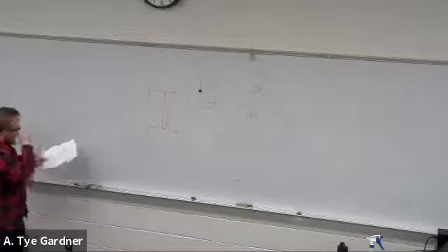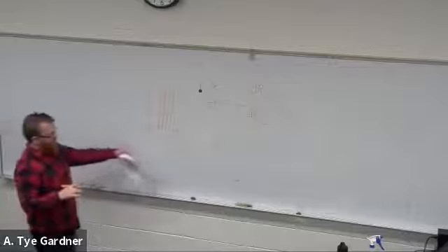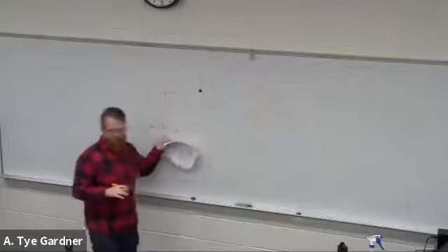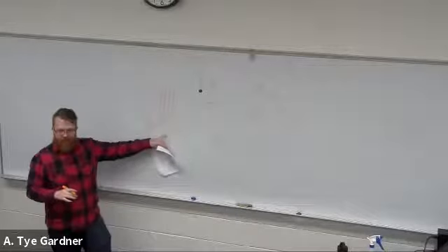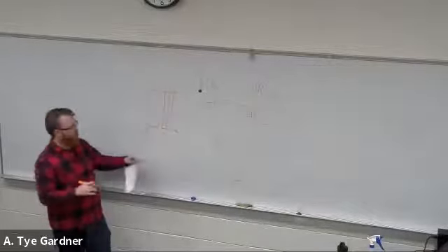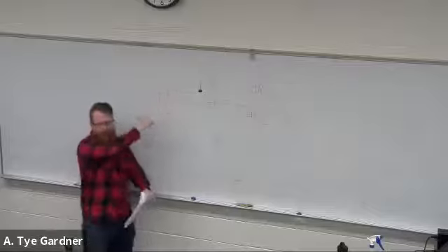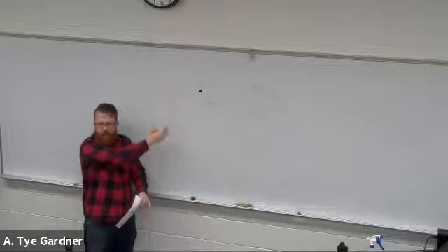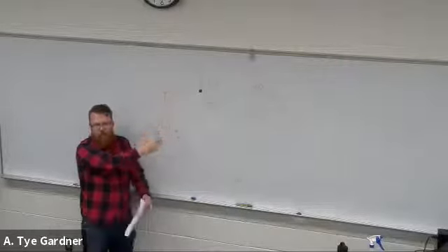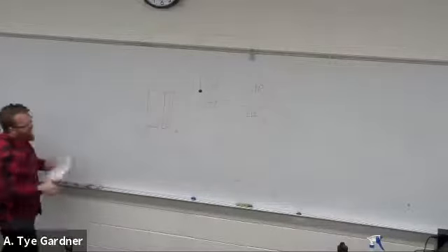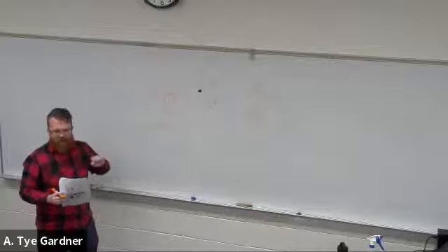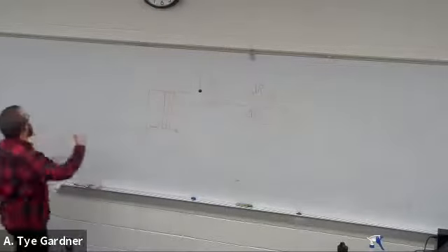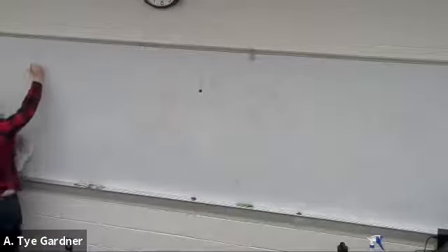Okay. So now this resistance though is not just strain, right? Because all we're measuring is the conductivity. We don't have a microscope that's measuring the length. We're just measuring how that resistance changes. So unfortunately for us, any temperature changes are also going to change conductivity. So what we end up with is saying that